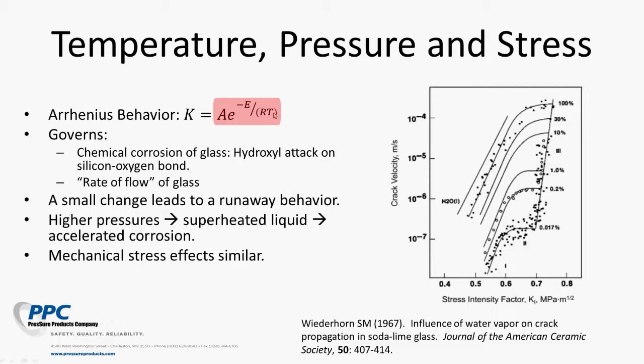The other important part of this equation is this E. Glass corrosion reaction is catalyzed by stress. Those of you who work with old pickup trucks probably know that those trucks start rusting right where the frame is most stressed. The exact same thing happens here. The effect of imposed tensile stress is described with this E value, which is the typical way of incorporating catalytic activity into a reaction rate equation.